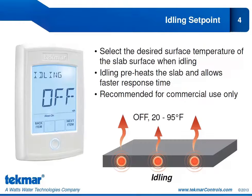We did discuss idling earlier in the training series, and we looked at how we can use it to maintain a certain snow-free area ratio. So this would be operating our SNOMELT system to maintain a minimum temperature during the entire SNOMELT season. And the applications for doing so would be more commercial applications. Typically you wouldn't use idling in a residential application because it will increase dramatically your energy usage.